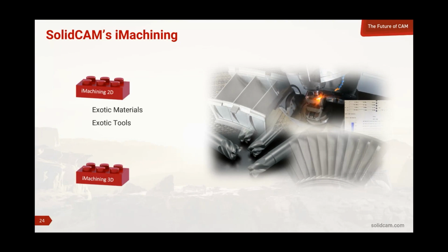The tools that you see there in the picture are actually ceramic end mills. Now, ceramic end mills give us much better tool life in this exotic material, but you have to be very, very careful how you use them. If you shock that tool at all, you'll cause it to crash. You'll destroy the tool. But if we can feed it in and out very, very smoothly, and we can never overload it at all, and we can keep the force load on it very, very constant, that tool will last an amazing amount of time cutting a very difficult material.